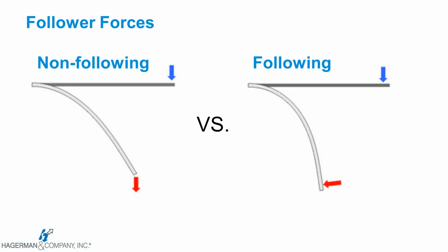And this is really, really important for specific applications. Obviously in this case, if it was some heavy mass that was pulling down on that component due to gravity, this isn't really all that applicable. But say, for example, I have a tank full of liquid, and I want to show the pressure on the outside or the inside of that tank, and use that information to see how the shape of the tank is going to distort. In that scenario, the forces are always going to push normal to the outside geometry, and as that geometry deforms, we need to make sure that the pressure is always maintaining that constant outward direction to our model. And in our case, we can see how this effect occurs in our environment.